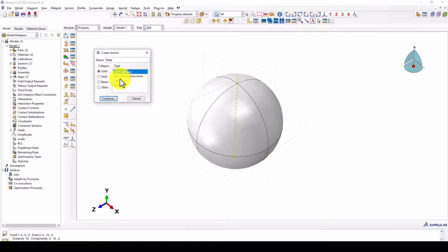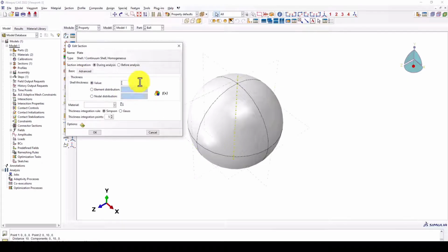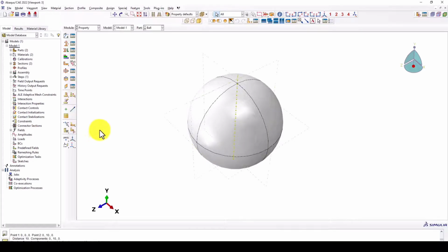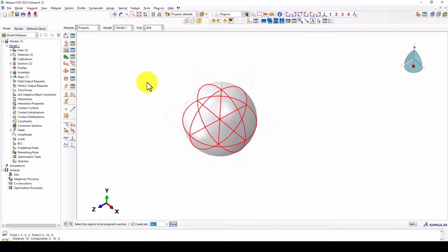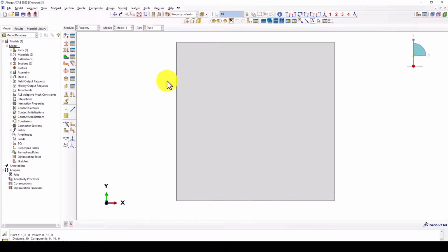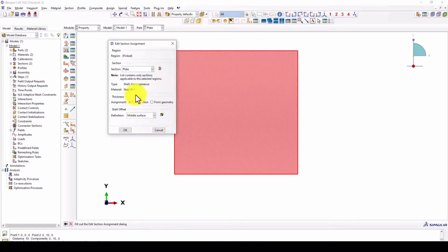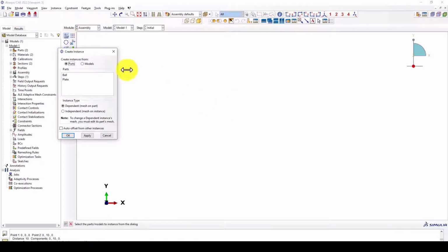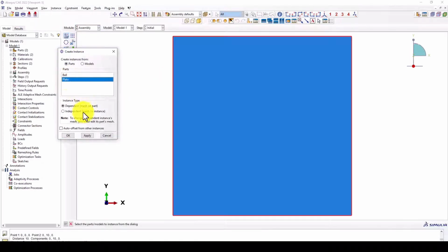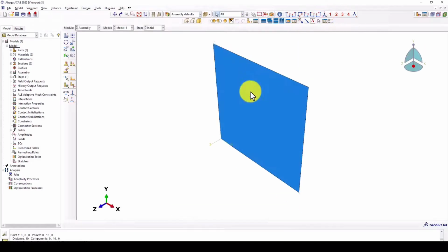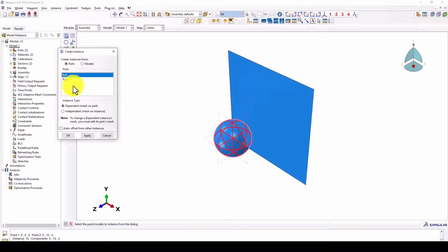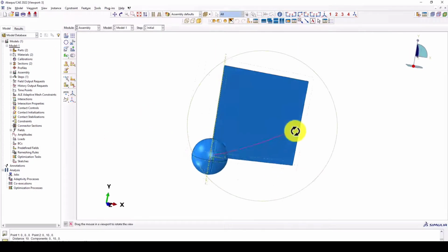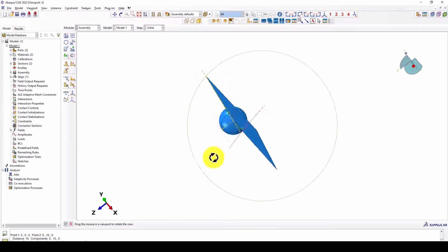Now I told you that impact problems are highly nonlinear and often involve severe contact and large deformation. Both are technically impact problems, that is the low velocity and high velocity, and the underlying physics can be significantly different, as I told you. Because in high velocity impact, we calculate severe plastic deformation. We get to see fragmentation, penetration, material failure at very high speeds, erosion and shockwave effects, generally visible in seismic loading conditions as well.